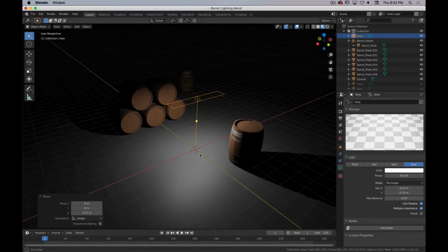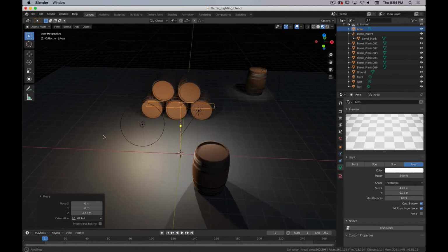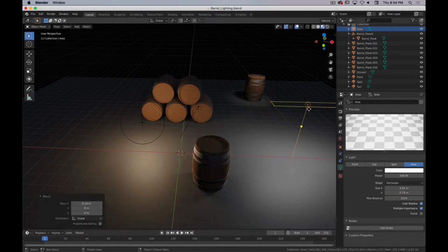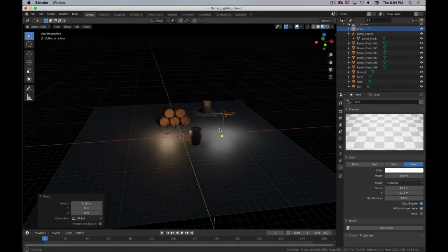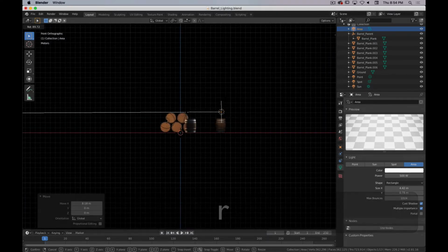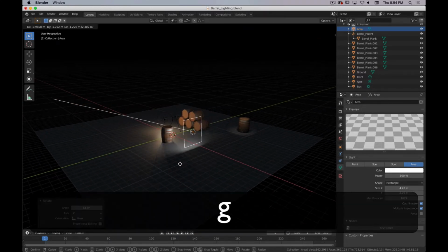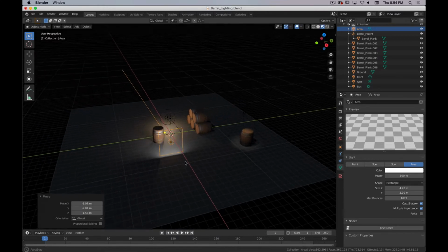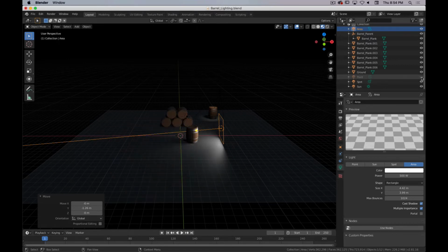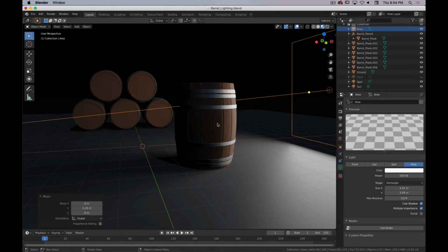And then obviously you can use them all together to create different effects. I'm going to move that one out of the way so we can kind of see. Actually, I use area lights a lot for kind of side light sort of things. So if I rotate this around and maybe I make the Y a little bit larger. A nice area light. If I hide the point again, you see it gives a really nice quality of light. It wraps around in a pleasing way.